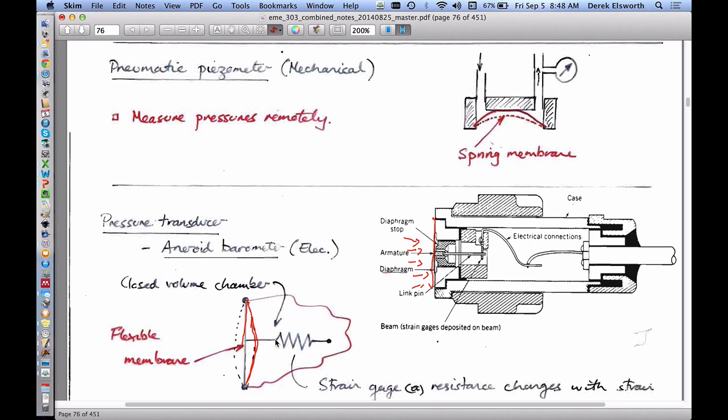And so typically the instruments you measure it with either are some strain gauge, which is typically something which as you shorten it or lengthen it, its electrical resistivity changes, and you measure that change in resistivity to give you a calibrated displacement, or you do it with a vibrating wire strain gauge.